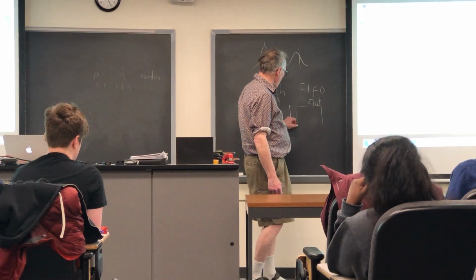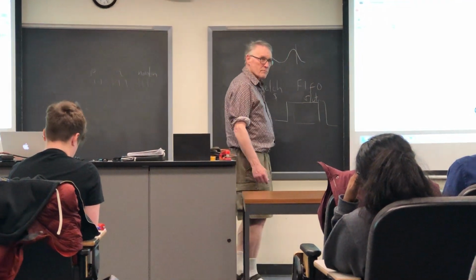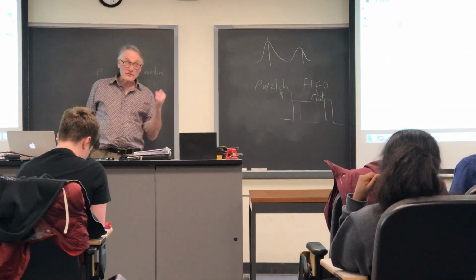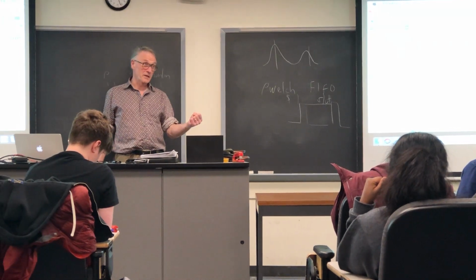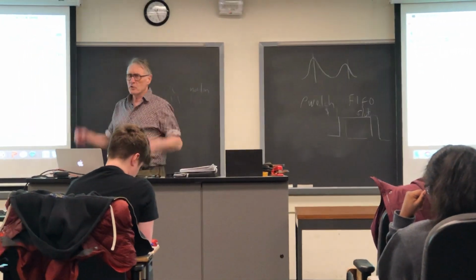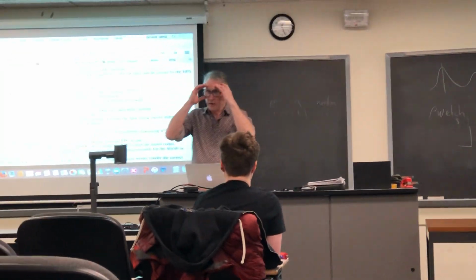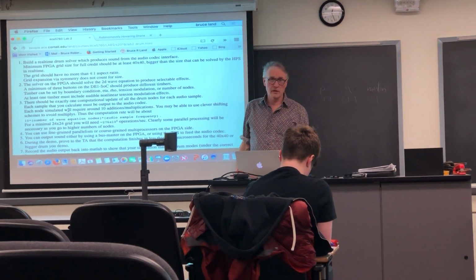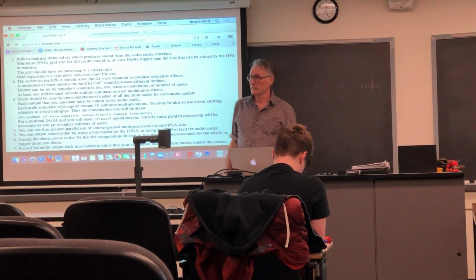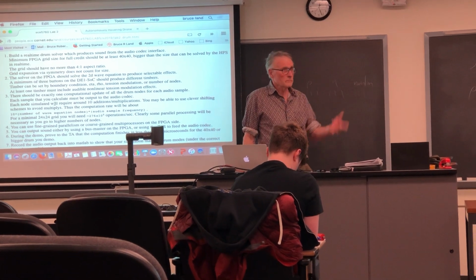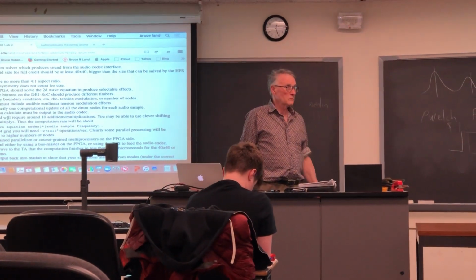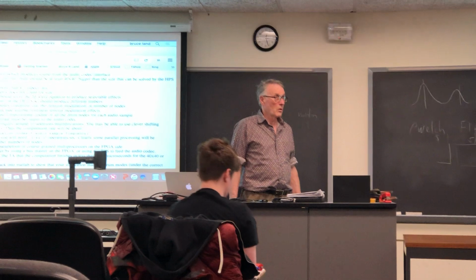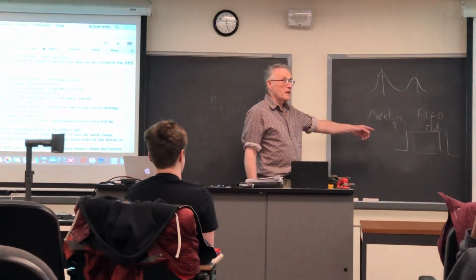Actually, it's going to be from the start of one to the start of the next one. So it's going to be from here to here. That's very convincing because it's a hardware readout. No interpretation, no calculations necessary. You just set it high when you enter that state. You set it low when you exit the state where you do run the solver. We should just show that it works synthesizing at 48 kilohertz. Like it has to meet the time requirement, right? Yes, this proves that it meets the time requirement.